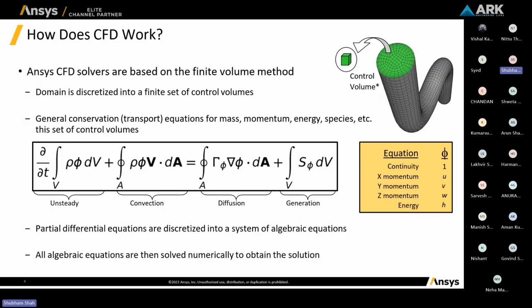So moving on to how CFD works. CFD works on the governing equation, also known as the general transport equation. This is the basic equation on which CFD works, which consists of unsteady, convection, diffusion, and generation terms, which are basically the X, Y, and Z momentum, continuity, and energy equations. This is a combination of partial differential equations. Then we discretize the domain into small elements.